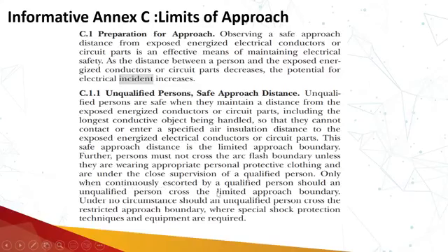Only when continuously escorted by a qualified person should an unqualified person cross the limited approach boundary. Under no circumstances should an unqualified person cross the restricted approach boundary, where special protection techniques and equipment are required. So this is for the unqualified person, and it covers all three types of boundary: limited approach boundary, restricted approach boundary, and the arc flash boundary.